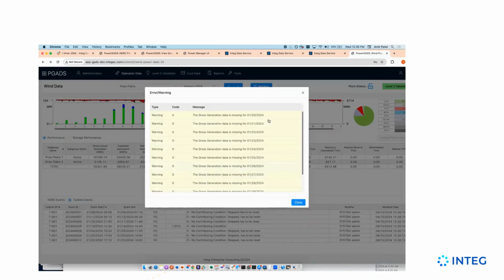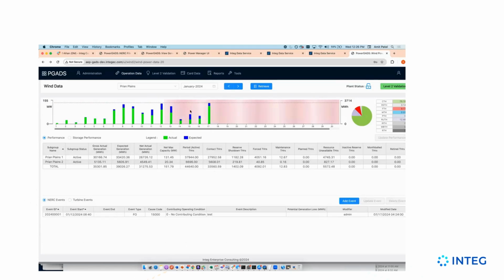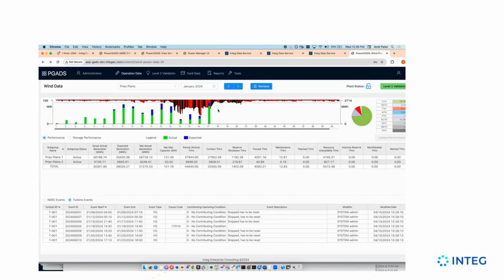So just don't minimize this, especially if you have stuff going all over the place. You can see here, there's tons of stuff going on, but if you have a couple turbines always out, once you hit that 20 megawatts, which is here, you are going to have problems getting the event ended. So just be very careful with that.